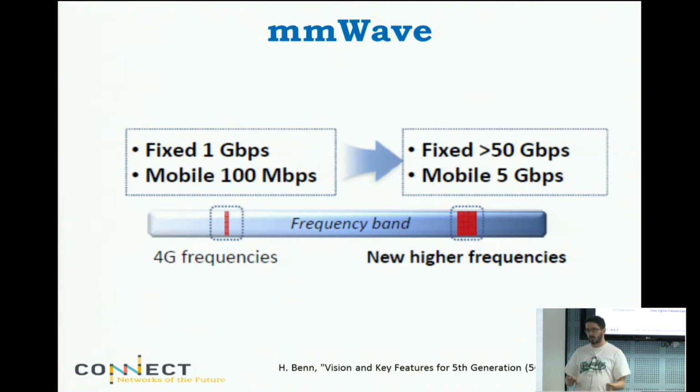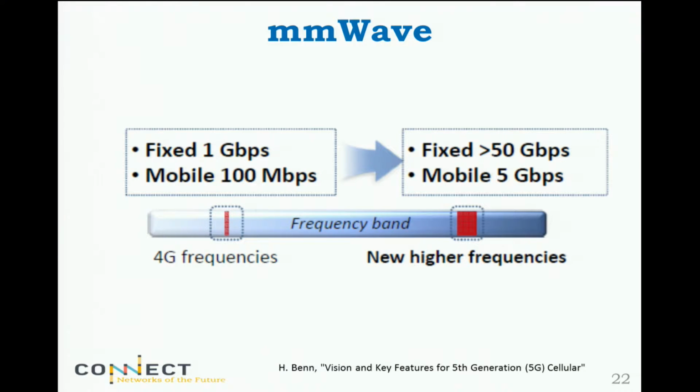The problem though is that if you start to do that with millimeter wave beyond some angle, you lose the signal altogether. So there are experiments showing, for example, that if you have a chest-worn antenna, you put the antenna here, you communicate with another person and you face each other, signal is good. As soon as somebody turns, then the signal is lost altogether. That wouldn't happen at lower frequencies. Okay, so there are some challenges that are definitely specific to millimeter wave.